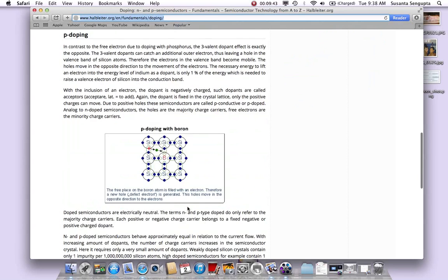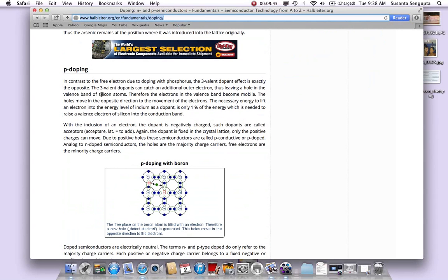Now the p-type. Similarly, what happens in a p-type? So p-type, let's take a material like boron. When you dope boron, let's say you're trying to dope boron into the same silicon. Every silicon has 4 electrons in the outside band, and the boron has 3 of them, which is shown here, 1, 2, 3. So if it has 3, one of them wants to satisfy this.